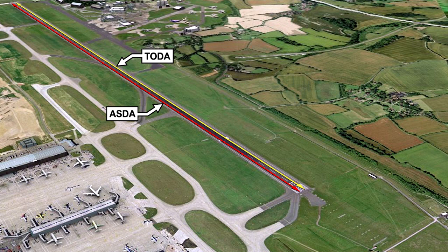In the case on screen, there are no stopways or clearways, but a field may also be balanced when the stopway and clearway are of equal length. In such a case, the ASDA and TODA are still the same. The term is used because many takeoff performance calculations can be simplified by using balanced field lengths. We will consider balanced fields when dealing with takeoff in the Class A section of this course.